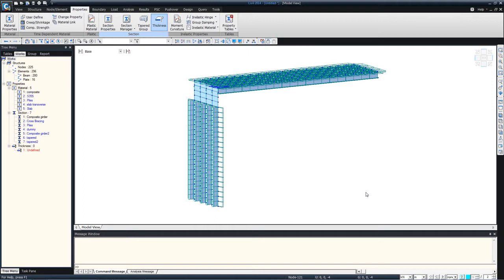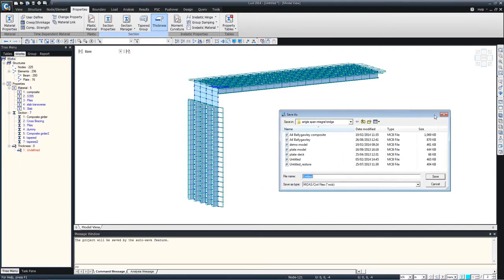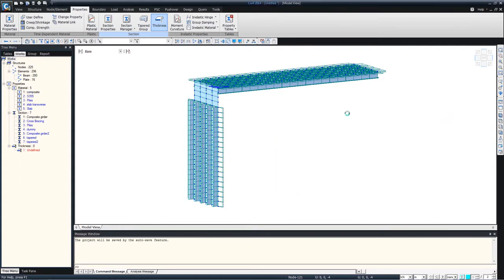Sometimes you can also use polylines, but I would not recommend using polylines every time, because polylines can have some problems with the intersection. It is always good to use lines whenever you have to generate arcs or any other type of geometry. So always break your arc into several segments and import them into Midas Civil, because the software directly deals with mesh.